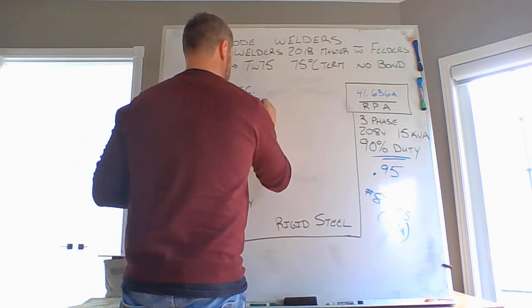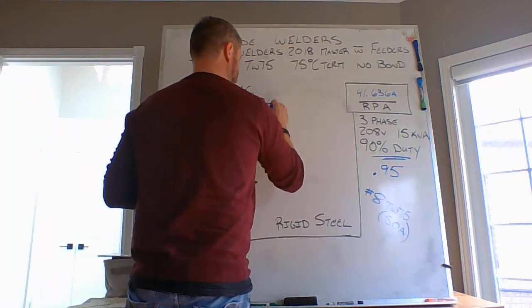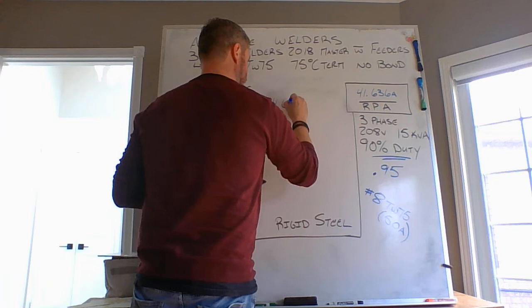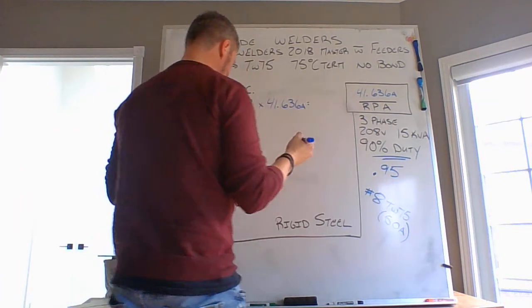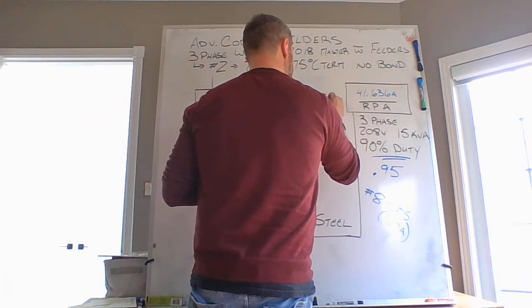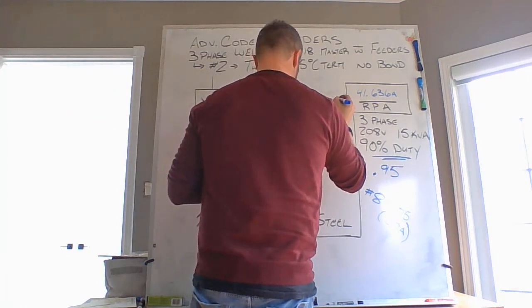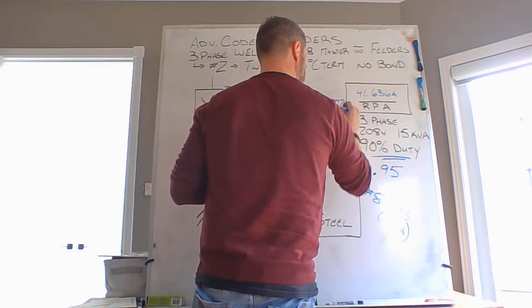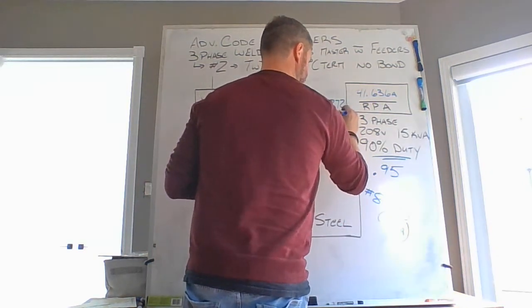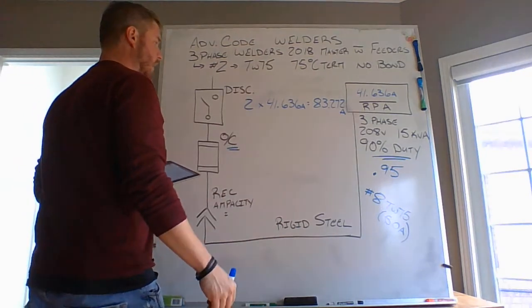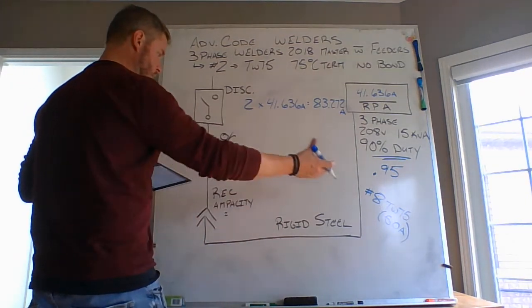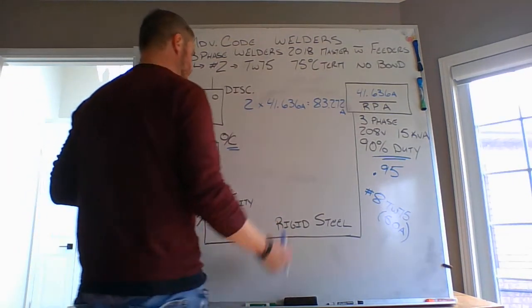So you are 2 times 41.636 amps, giving you a calculated value of 83.272 amps, or 200% the capacity of your conductor, in which you chose number 8, TW75.